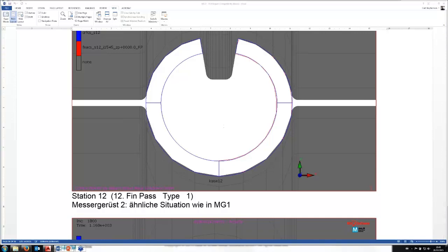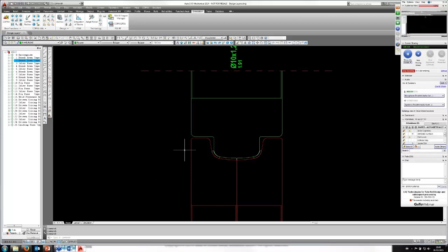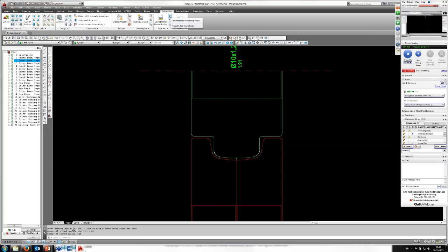So in addition to that, we mentioned earlier the possibility with CAE technology, so we can export our design directly into FEA for verification. Once we've completed our design, of course, we can now use the software to generate our standard roll dimensions, our assembly plans, for example. So we can very quickly and easily generate two-dimensional assembly plans. Our bill of materials, our cutting list here that we would send to our steel supplier, for example, for cutting our steel.